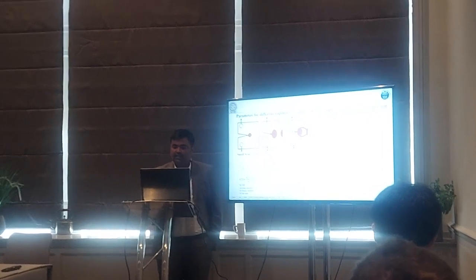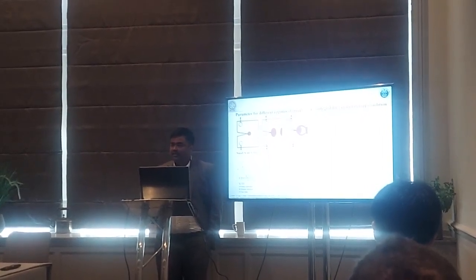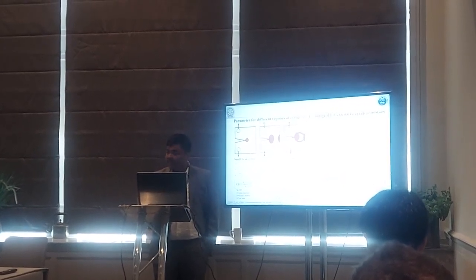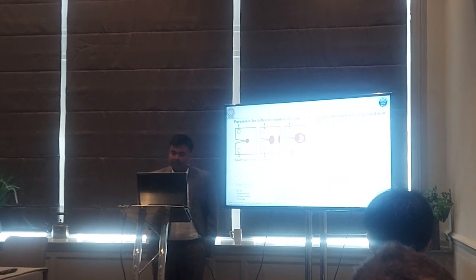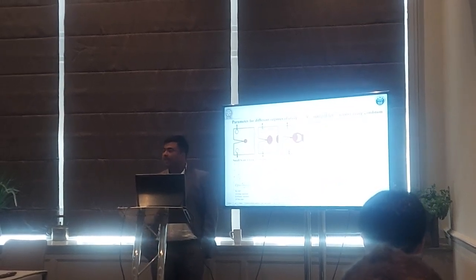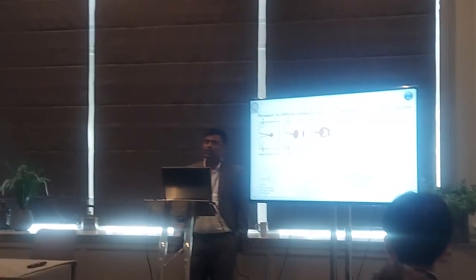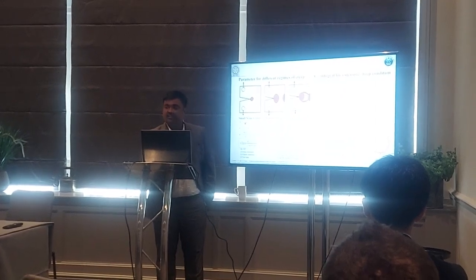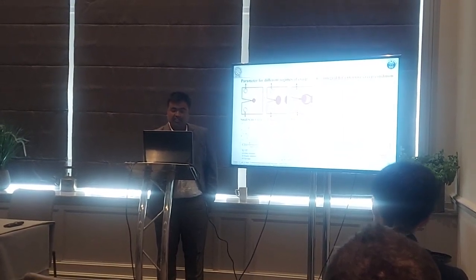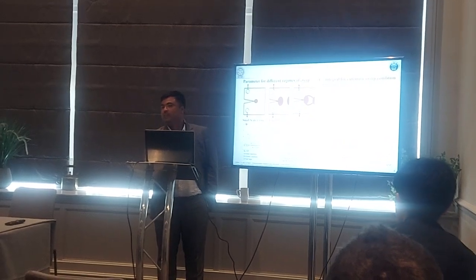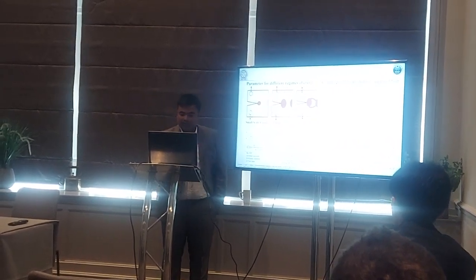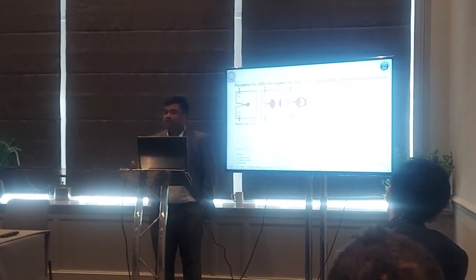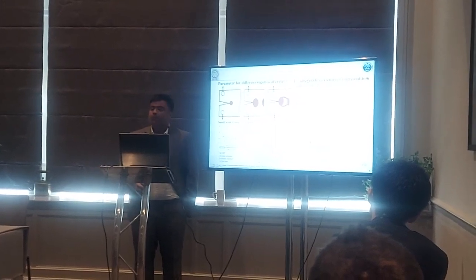We can find it with the help of the stress strain graph. But in steady state power law creep, the deformation is time dependent. So here the strain rate is given by Hoff's analogy, which says the strain rate is a function of stress. When this condition is valid, then we can apply C star. But this condition fails in the case of small scale creep, where the strain rate is a function of stress rate. That's why we cannot apply C star here. C star is similar to J: J is path independent, and similarly C star is also path independent.